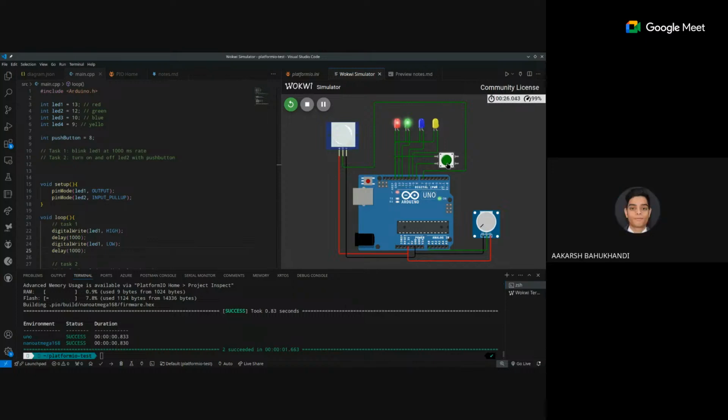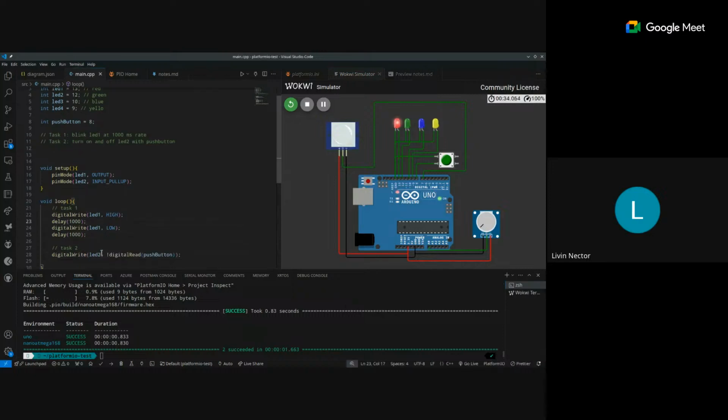We haven't set the delay time. That's because when it is doing this, it is not doing this because it's waiting here without coming to this line of code, right? Yes, sir. So that is blocking the other task's code. So this is a blocking delay.